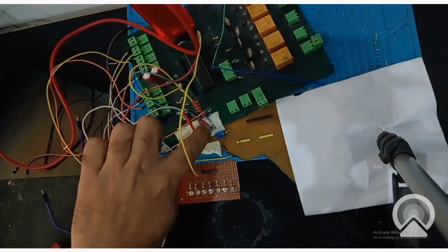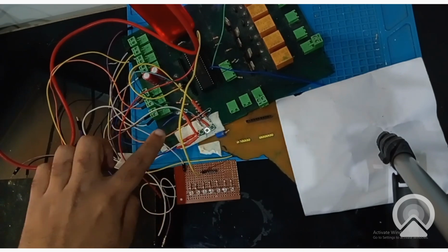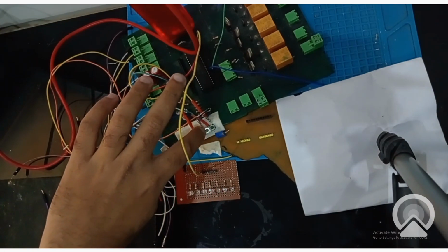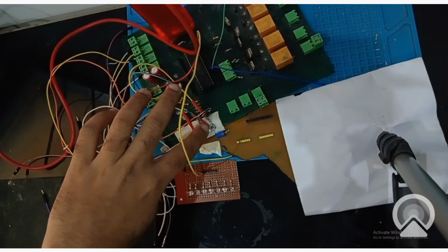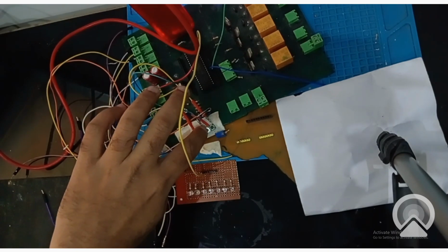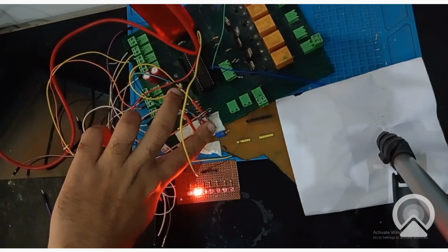See, I press one button, no LED turns on, press the other button, no LED turns on. I press both the buttons, now the LED turns on. Now that's the AND gate. Only the LED will be on, output will be 1, if both the inputs are 1. See, both inputs 1, LED is 1. I press one input, nothing happens, second input, nothing happens. When I press both, the LED turns on. So that's the AND gate.